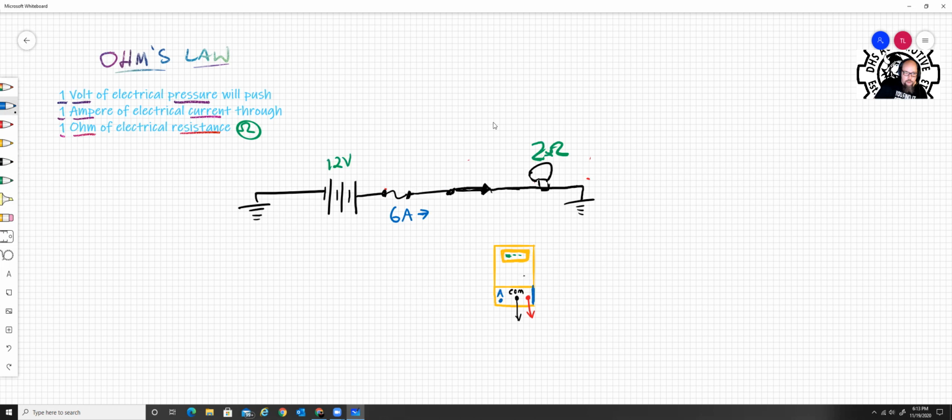What you would do is remove the little lead out of the volts ohms jack, and take it over and put it in the amp jack.